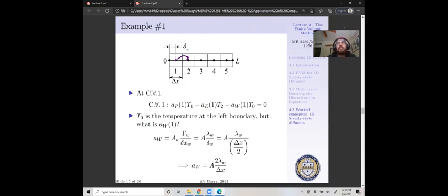And we contrasted this to the finite difference method, where in the finite difference method, right, we created a ghost point out here, and we did a little bit of algebra and solved for the temperature at our boundary based upon what was happening on the inside. That was for a given flux condition. Here we don't have a given flux condition. We're going to talk about that momentarily.